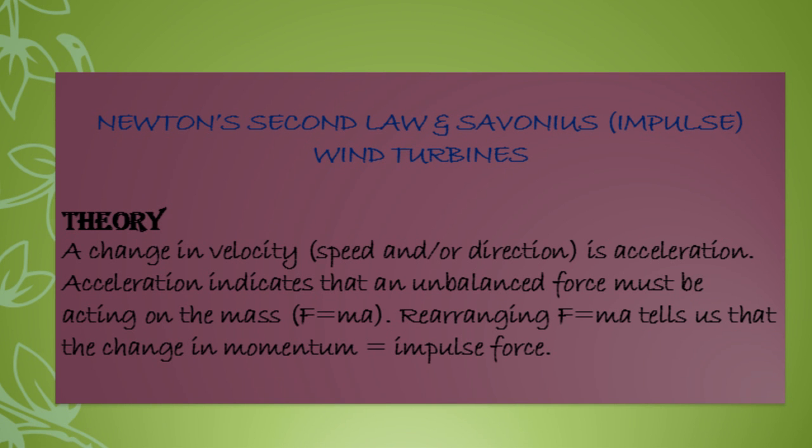And what does that mean in terms of a wind turbine? That is, wind turbines pick up some of their kinetic energy from the deflection of the air as it hits the blade. Air blowing onto the turbine blades is forced to change its velocity at constant pressure. A change in velocity creates a change in momentum of the air mass, which indicates that a force must be acting, that is Newton's second law. This rotation arising from fluid deflection is a feature of impulse turbines. Wind turbines also have features of reaction turbines.